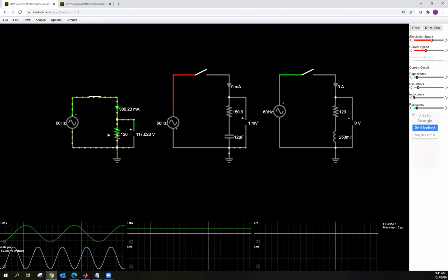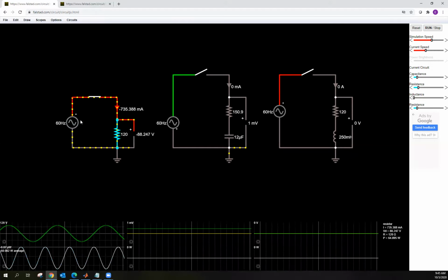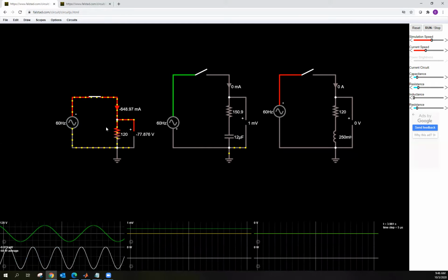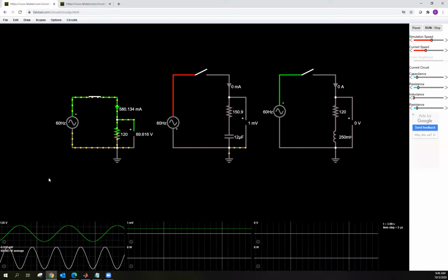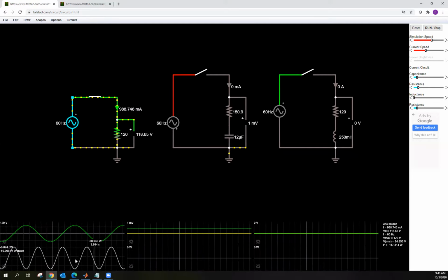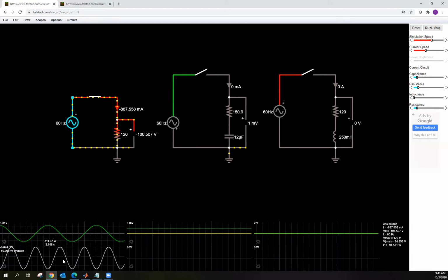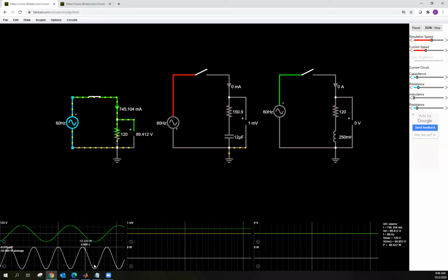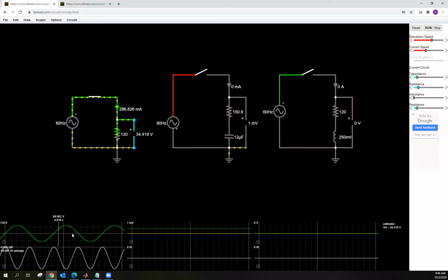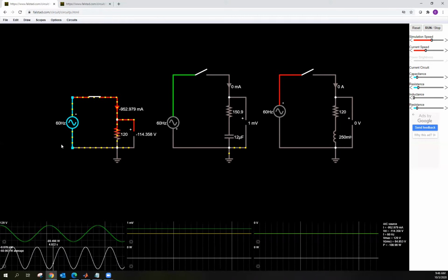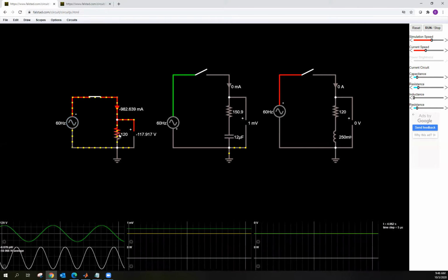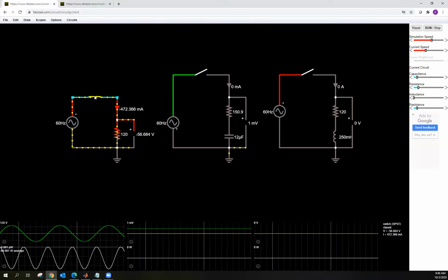The power factor in this case would be 1. All the apparent power is equal to the real power, and so your power triangle for this would be a horizontal line. Hopefully this makes sense. Notice that the instantaneous power is still oscillatory, and it is 2 times the frequency of either the current or voltage. So here is an AC power situation, single phase with just a resistor. Okay, I'm going to turn this off so it's not as distracting.